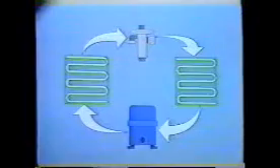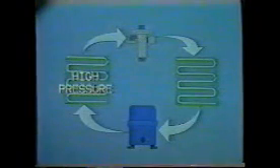We're ready now to move on to the next component in a refrigeration system. We've seen evaporators and compressors, so now we're going to take a look at condensers. The condenser is located in the high pressure side of the system. As you'll recall, the function of the condenser is to change the high pressure, high temperature vapor from the compressor into a high pressure liquid.